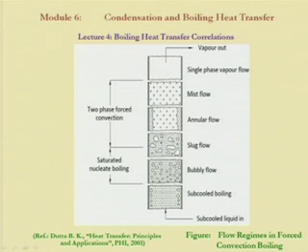Okay. And then in this region, more bubbles are getting formed, and there is a mixture of bubbles in the liquid. This is called a bubbly flow. This flow is happening in the same direction as the flow, and it is called a bubbly flow. Then with further increase in temperature, some of the bubbles will coalesce and bigger bubbles will form. This is called a slug flow situation, where big vapor bubbles are coming up, and after that you can see that there is an annular region.